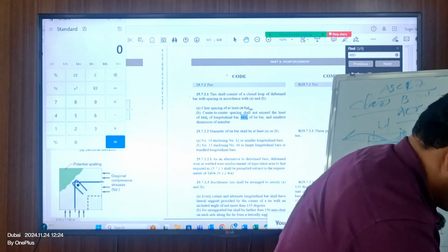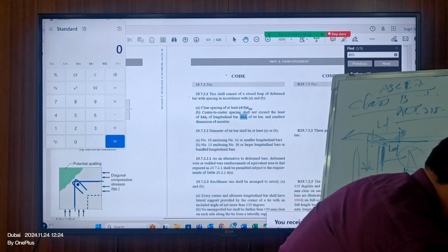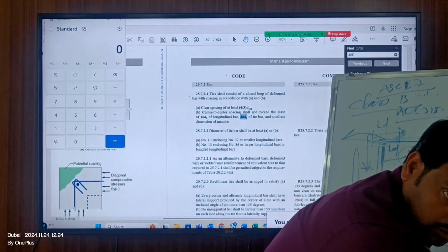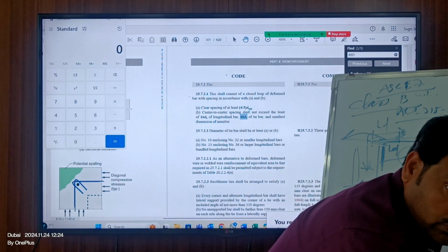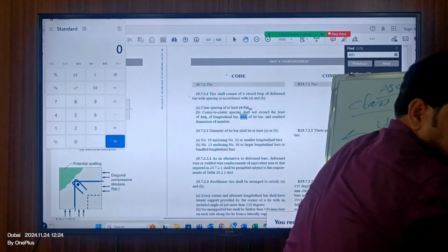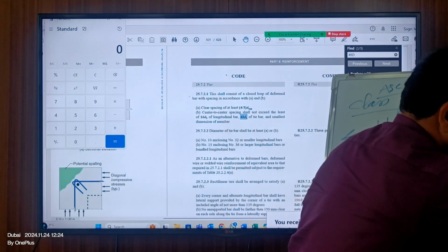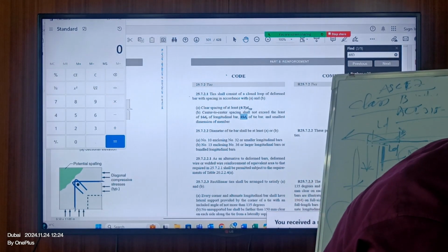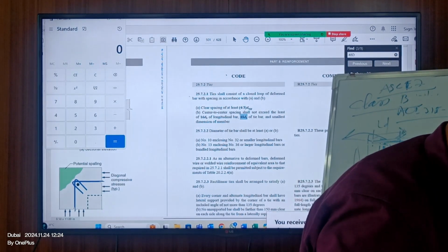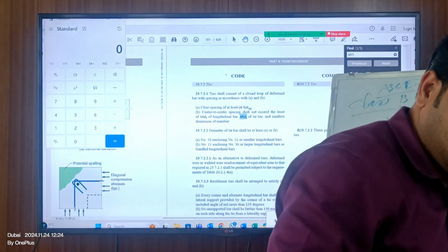But the moment when you are talking about support actually, I will take the moment from here to here. I will never start from here. You get the point? The similar funda for the raft here, the columns actually, then the shear is starting from here, right? That's what you are following, to compensate the shear, isn't it? But right below here, why should I? This is only for the purpose of confinement and the stability of the rebar actually.